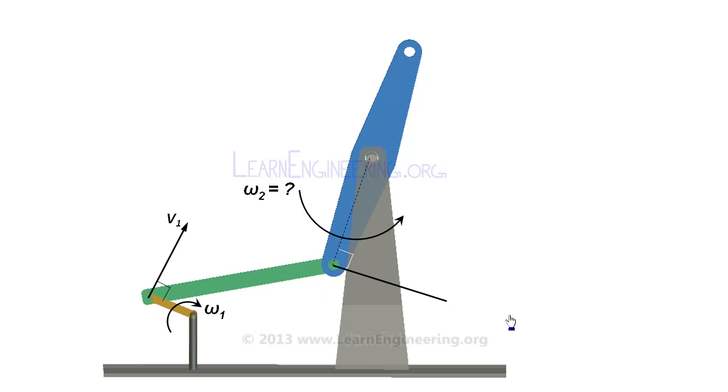Here the first concept we learned comes to help. Since this bar cannot elongate or contract, relative velocity between these points should be perpendicular to this link, which will lead to magnitude of velocity at point 2. From here, angular velocity of the link can easily be deduced.